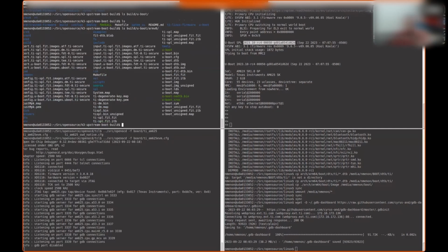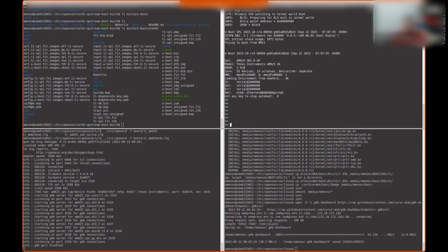Now, U-Boot has two stages of booting. The first stage is where U-Boot has not done a relocation of itself. Right now in the shell that you see here, it has already completed its relocation. If you are debugging U-Boot prior to relocation, there is a slightly different step you have to follow versus the step after the relocation is complete. All this is part of the U-Boot documentation, so no big deal there. But this is something to be aware of. Otherwise, you'll be like, I loaded my symbols, but it doesn't show that, right?